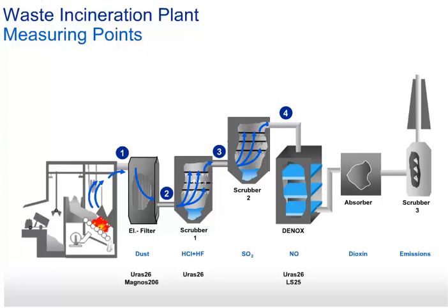Monitoring the ammonia dosing to the DeNOx process. Activated charcoal filter to remove dioxins and hydrocarbons. Safety measurement to monitor random occurrence of partial self-ignition of the activated charcoal. Emissions monitoring according to local legislation with ACF-NT, for all components CO, CO2, NOx, SO2, HCl, and HF, plus multi-FID 14 for total hydrocarbon measurement.